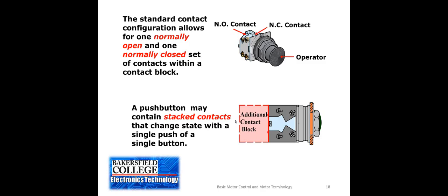So we can stack 2 or 3 or 4 of them depending upon how strong the springs are. If we get a whole bunch of them in there, it adds to the amount of force that needs to press the switch. So after we stack maybe 3 or 4 of them, then that switch is going to be too difficult to press. In that case, we may need to build the rest of the contacts by using control relays rather than just relying on the switch itself.